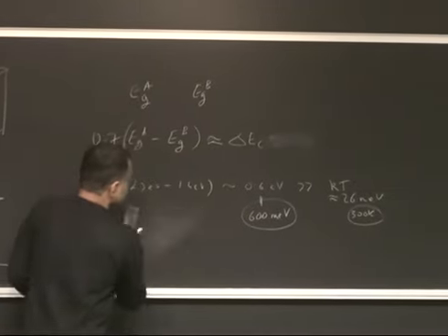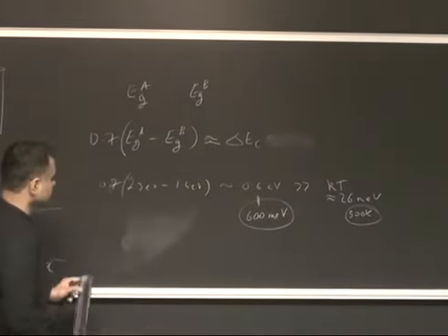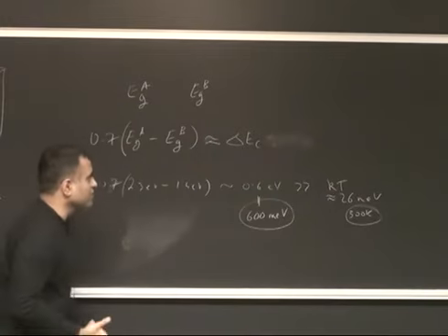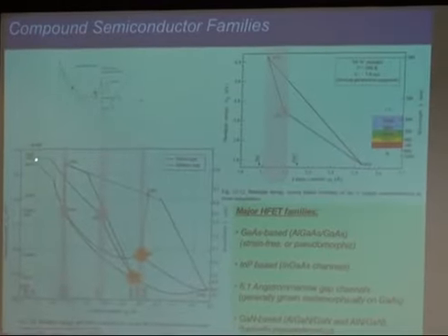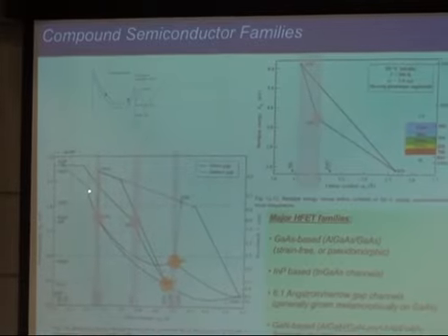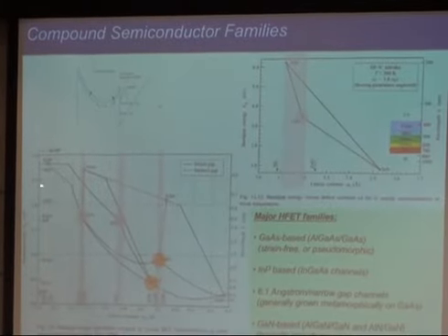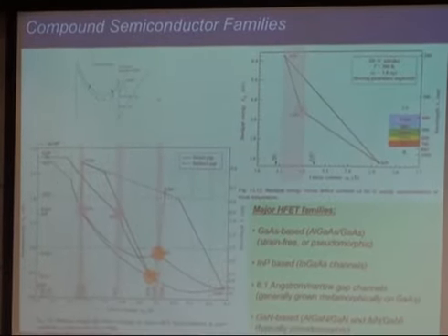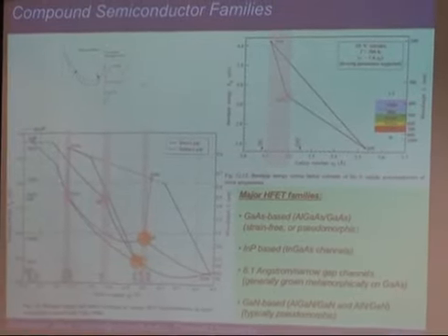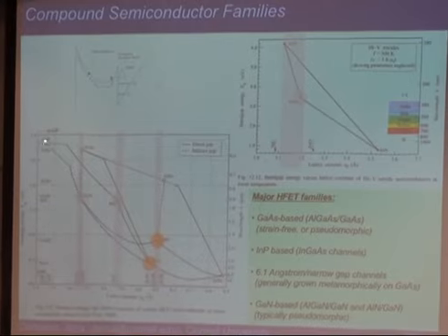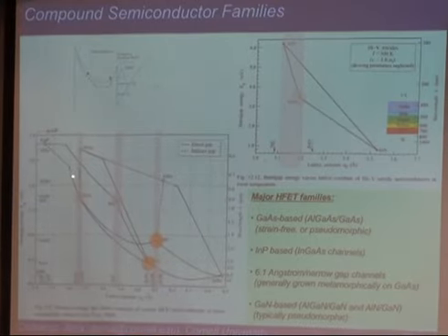Okay, so now you can see you have a complete freedom in design. Instead of choosing aluminum arsenide, you can actually choose, let's say, here, which is maybe 1.7 eV. Typically, what one would use is like 30% aluminum gallium arsenide, so this is 100% aluminum. You kind of come here. You reduce the barrier height for various reasons, and those reasons we can discuss later.